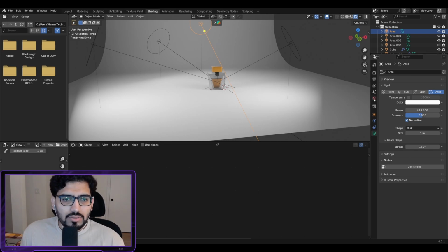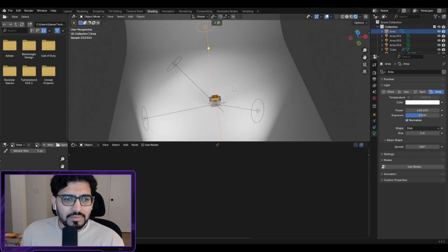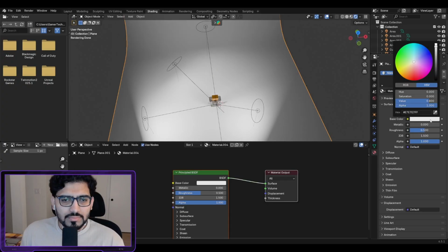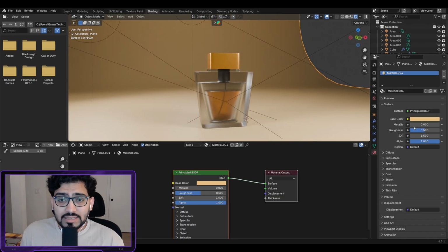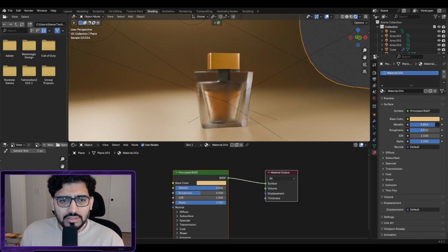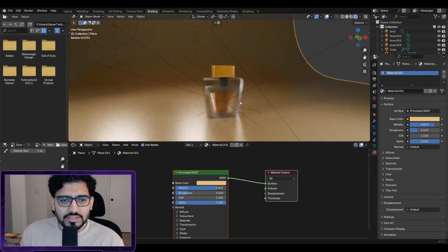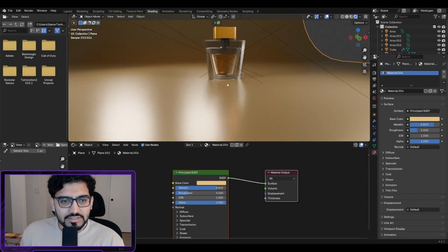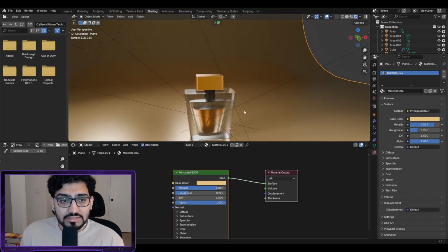All right, and what I also like to do is, because all the lights are set up now, we'll apply some material over here. Let's set the material in a same fashion, but not exactly the same color. I'll put it as light as I can, but we'll apply some metallic over here as well to make it look dark, and then we can reduce the roughness to a point where the reflections are slightly showing up. Now it gives a good image of your product because the reflections are fading out slightly, if you can see, and that is cool.